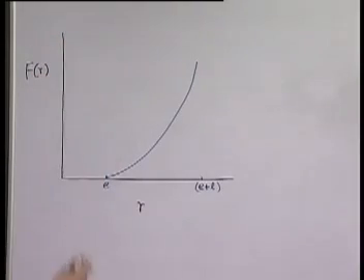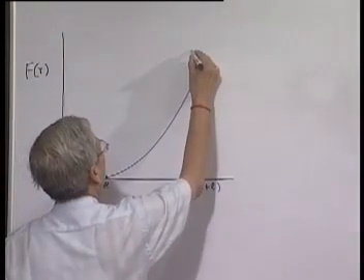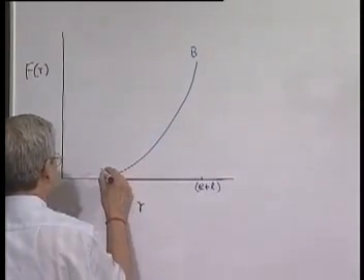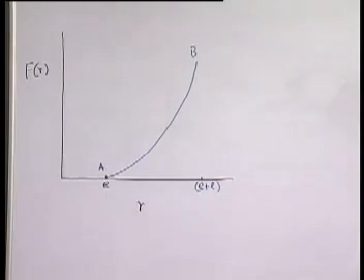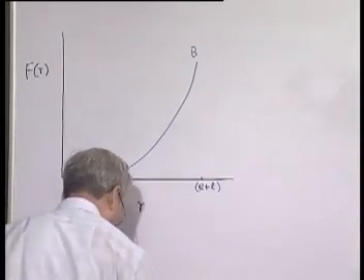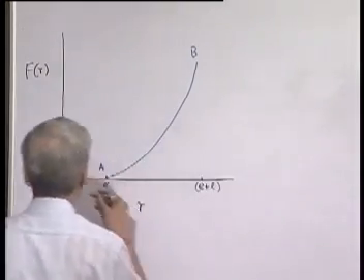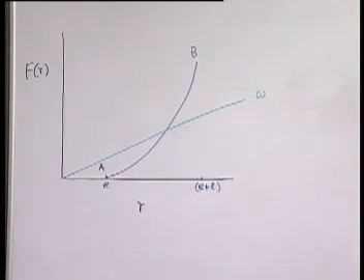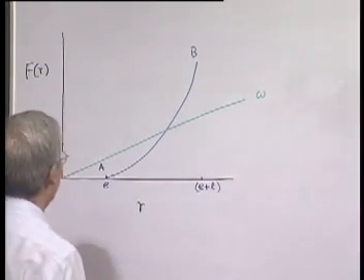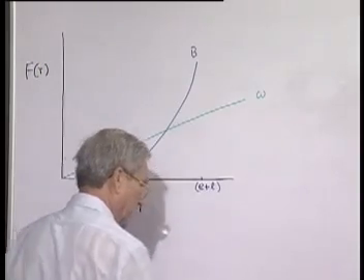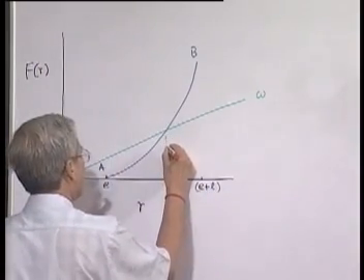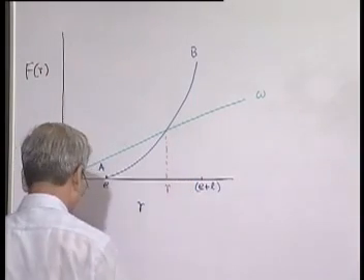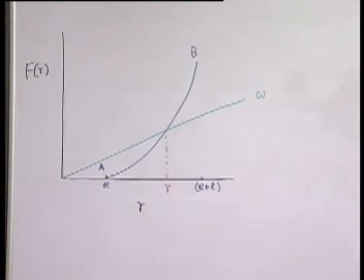It tends to become infinite, and this is the control force curve for the Porter governor with this kind of configuration. So, therefore, we find that if we now plot the centrifugal force, which will be just a line for a particular omega, and the slope of this line will depend on the omega, because the slope is nothing but m omega square, and this will be the equilibrium position. If the governor rotates at this speed, then this radius at which the balls will be is this intersection.